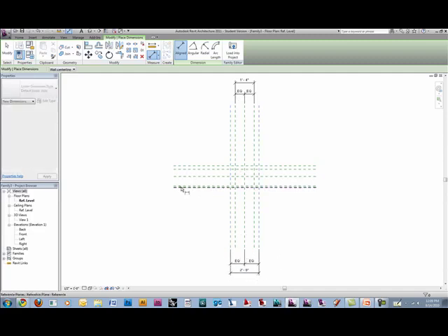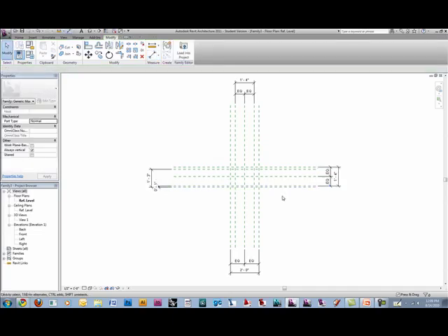With this, we're going to do from the first line to this third line, but we're not going to tell it to be equal because that's the seat depth, but the seat depth is not going to be centered around this line. However, the overall depth will be. So from this second line back to the last line, that depth will be centered. And we need to do maybe a dimension right here. So I basically set up all the dimensions we need really quick.